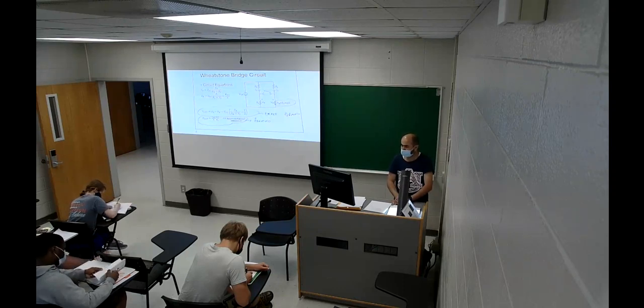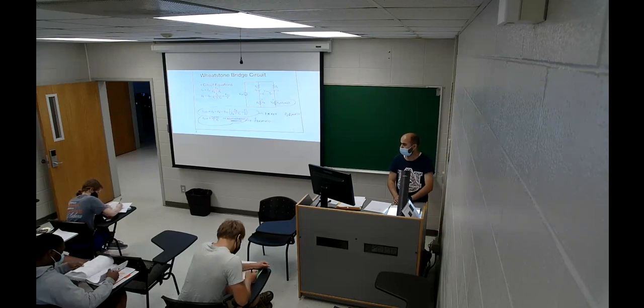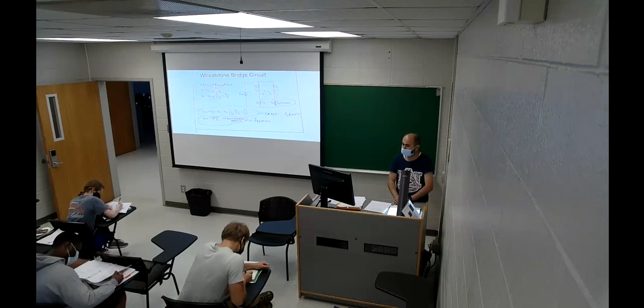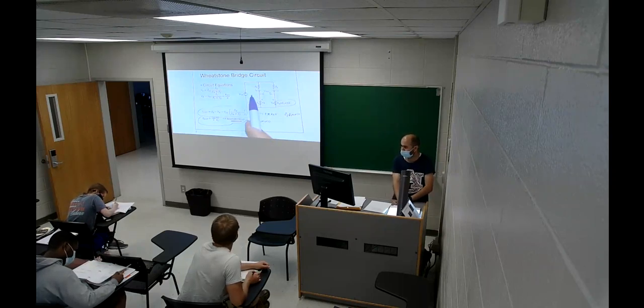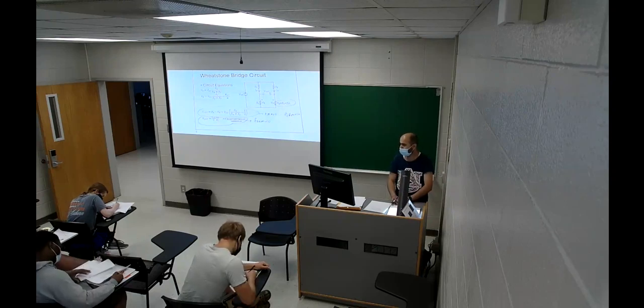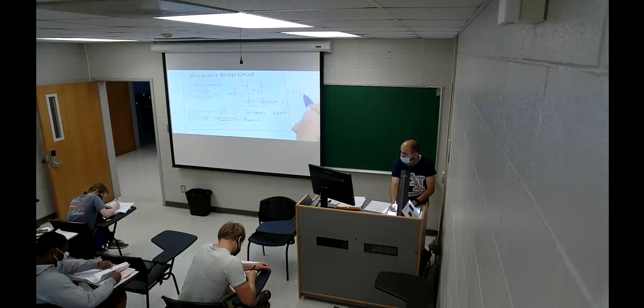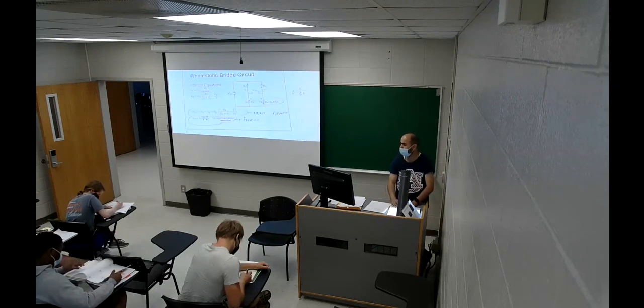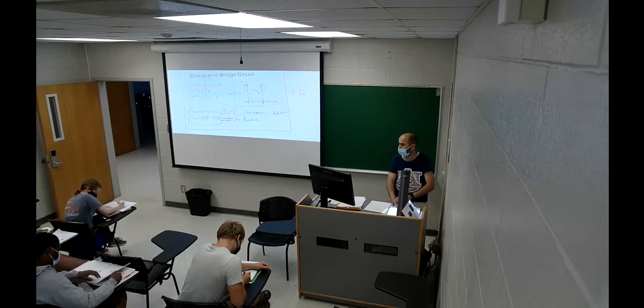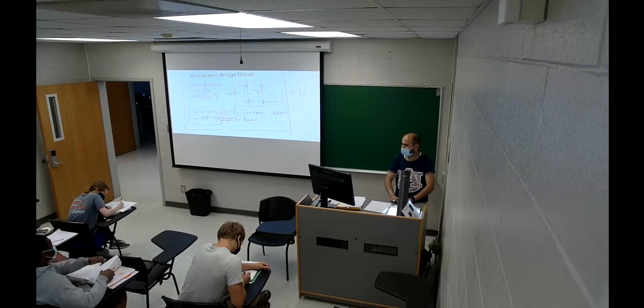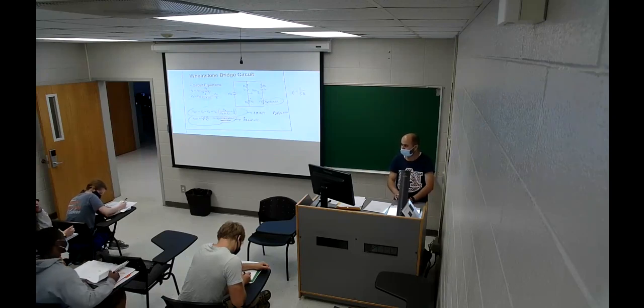We are using a device called Megger. This device is used to determine at what distance the fault is happening, and it's very accurate. This device is based on the Wheatstone bridge. We can find the unknown resistor, and we know resistance equals L over sigma A. We have the cross-section area, we have sigma, then we can determine the length. Then if we determine the length, we can say, for example, after 200 meters there you can find the short circuit here. Then you can start digging, find the short circuit, solve the problem, and return the electrical service.